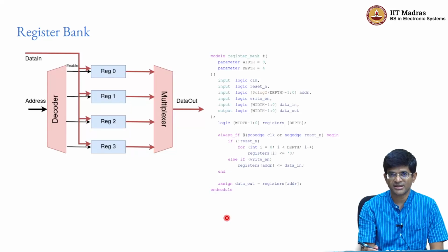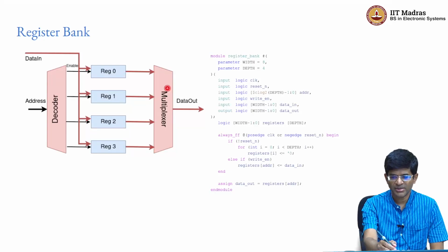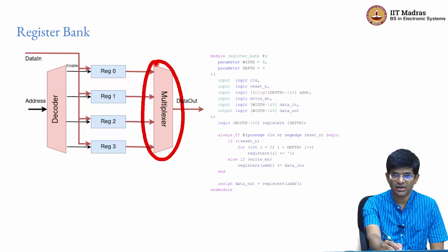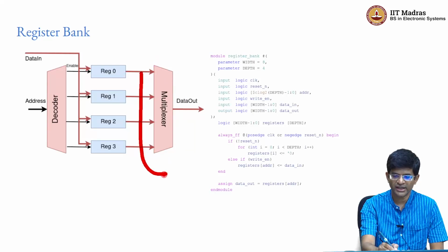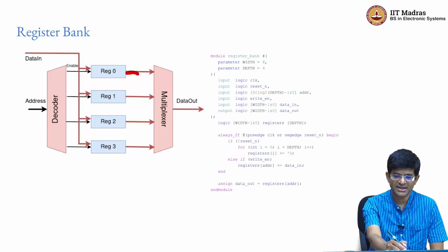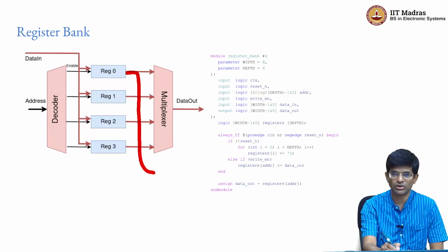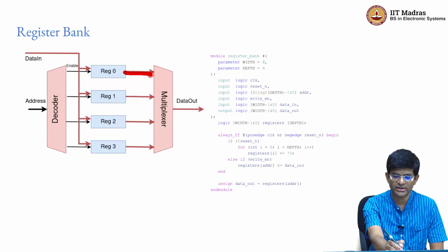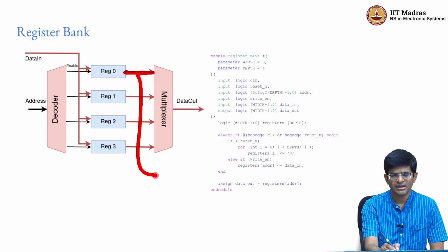So this is the basic structure of a register bank, and as you can imagine, over here I have a single data output. I could also have chosen to take all these 4 values out into another multiplexer and had one more output coming over here, right. So I can have 2 register values being read out at the same time, and that's not really much of a problem because all that it means is there's a little extra additional fan out on these pins. They just need reg 0, instead of being connected to one multiplexer, needs to be connected to 2 multiplexers.